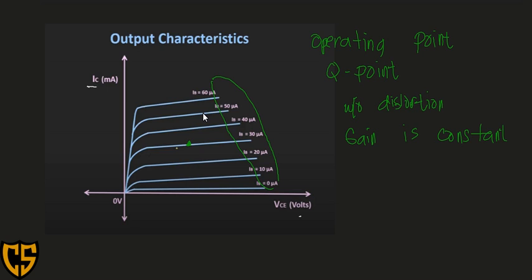Of course, during the period of operation, our transistor heats up, so it will affect the operation or function of our transistor. So stability in reference to temperature, and at the same time stability in reference to external factors. Because if our transistor is heating up, or there is a variation in temperature, our beta is affected. So what is beta?